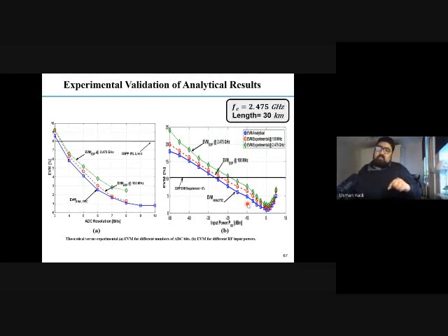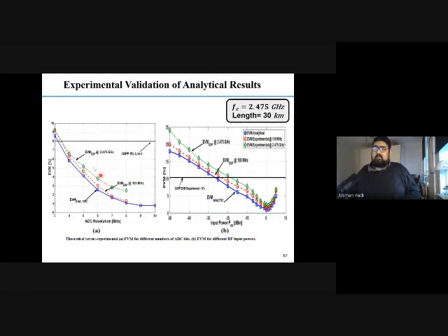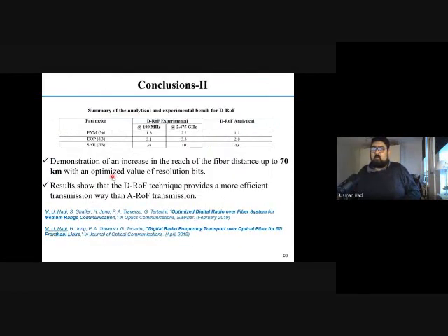That is, you can still have images of the carrier at those particular bandwidths. That is why you see that 100 megahertz is the image of the EVM at 2.4 gigahertz of carrier frequency. We just want to show that the 100 megahertz undersampled image of the carrier has better performance, because the lower the carrier frequency, the fewer interferences you have. So maybe I will just pass on. The idea was to show you that digital has better performance as compared to the analog one.